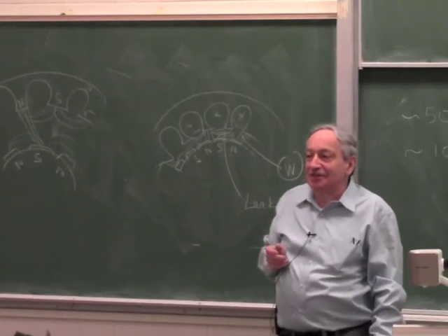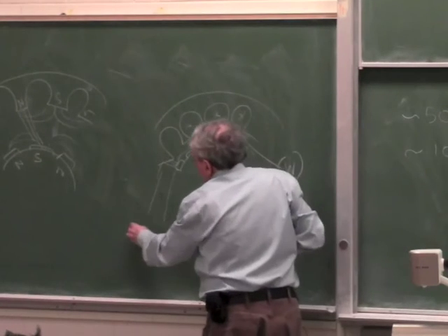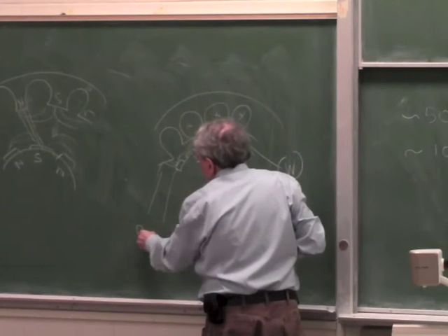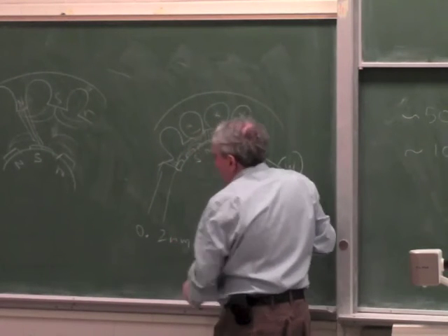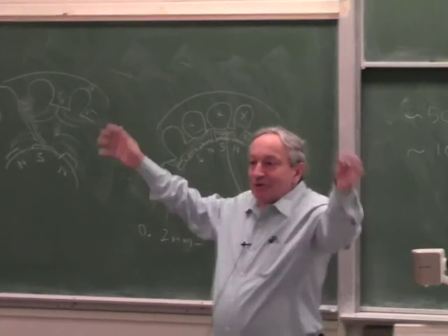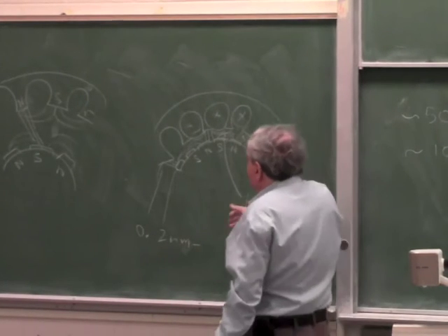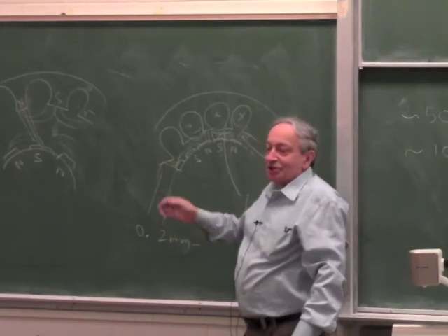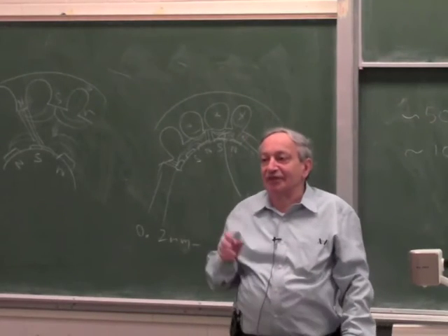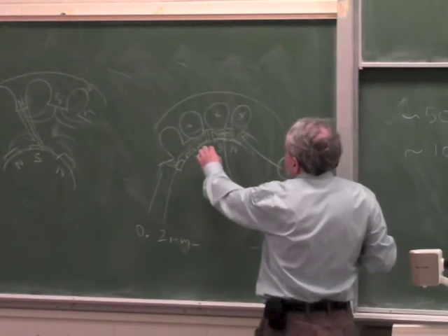Okay, so in a stepper motor, the air gap is about 0.1, 0.2 millimeter. Let's say more like 0.2 millimeter. In a big motor, like an industrial motor, it's like 1 millimeter, because a big motor is harder to make accurate. Now the real problem with that: you can make the gap smaller without touching, but then the motor will have irregular torque and cogging. Because imagine that this rotor is a bit eccentric.